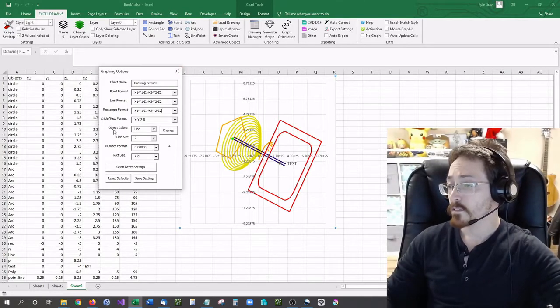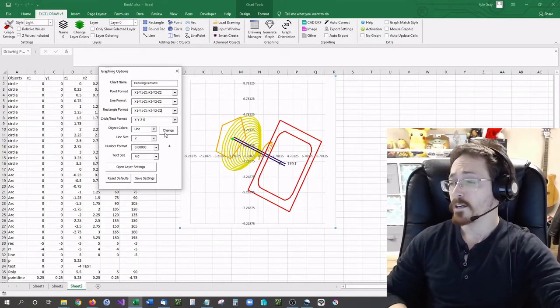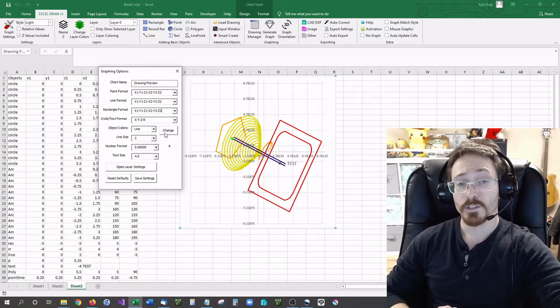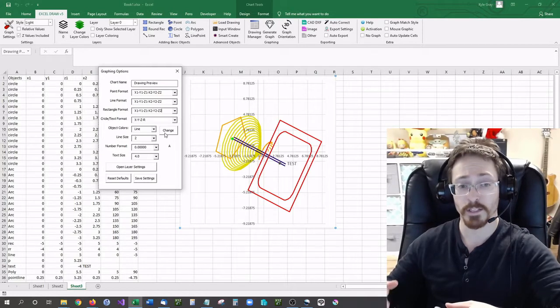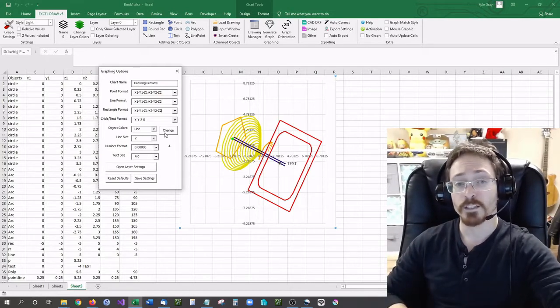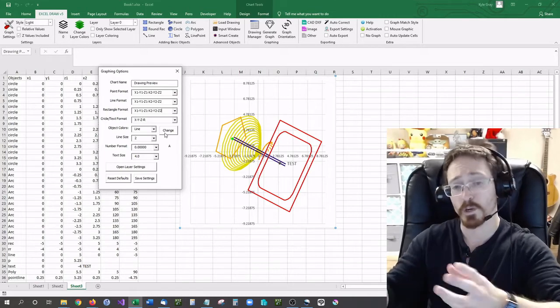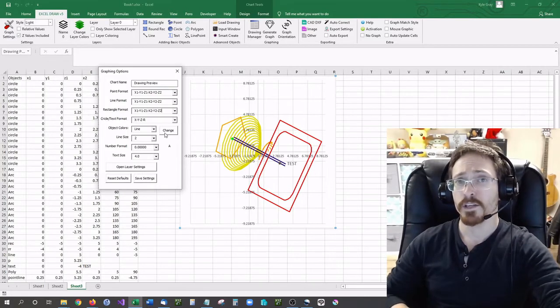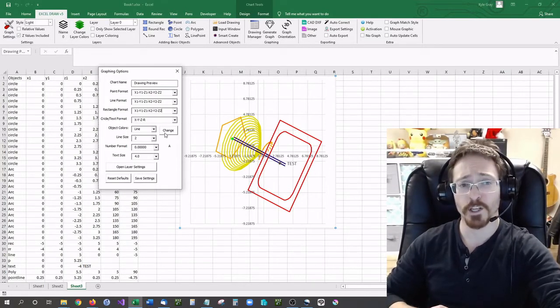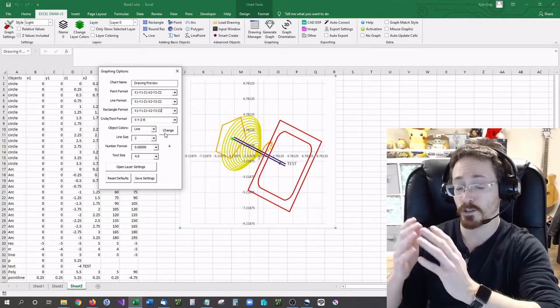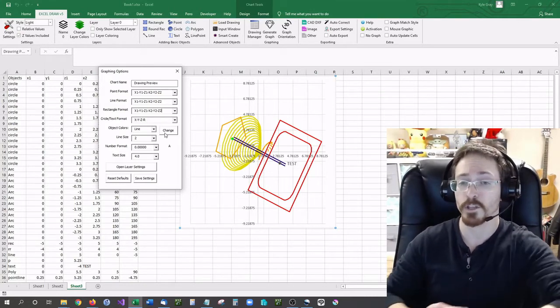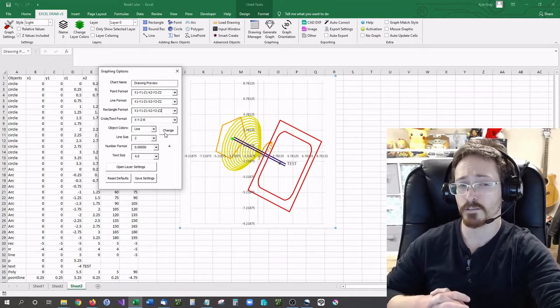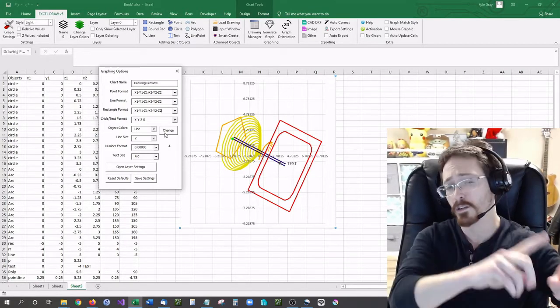Next, if you would like to ever change the color of something: color was originally put into XLDraw based on shapes, to distinguish between different shapes, what they were, and easily recognize them. Whenever XLDraw moved into the third dimension, and you were able to rotate it, and layers started being added in, the color scheme needed to change, so we changed it from being based strictly on objects to also being based on layers. How you change the colors of a layer is you link it to the color of an object.